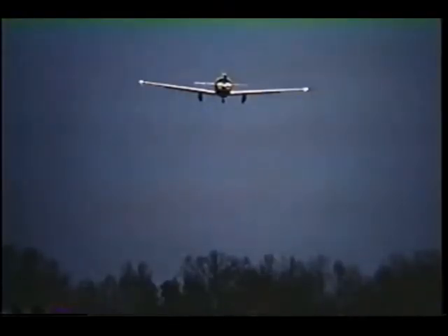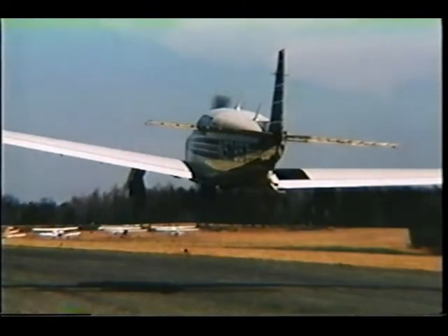Now let's make everything exactly the same, except that in this second example, you've been tooling around by yourself all day, so your landing weight is much lighter. But you still opt to carry the same short final approach speed as before, 1.3 VSO at max landing weight. And lo and behold, your intended point of touchdown whizzes by beneath you. Why? Because you're still floating in ground effect.